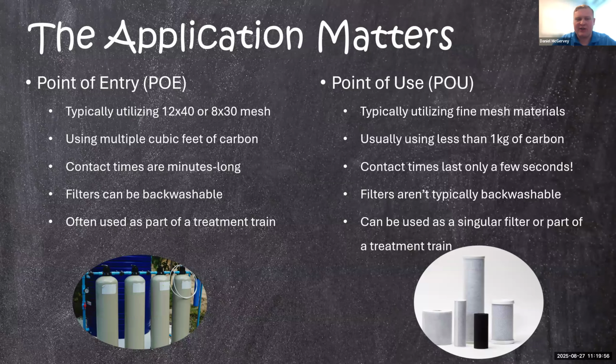And often these are used as part of a treatment train. So maybe they're not the only process going on, or maybe there's multiple containers of carbon all being utilized in a series or parallel formation to make sure you're getting all the water you need through the carbon with the right contact times and hydraulic loading rates.